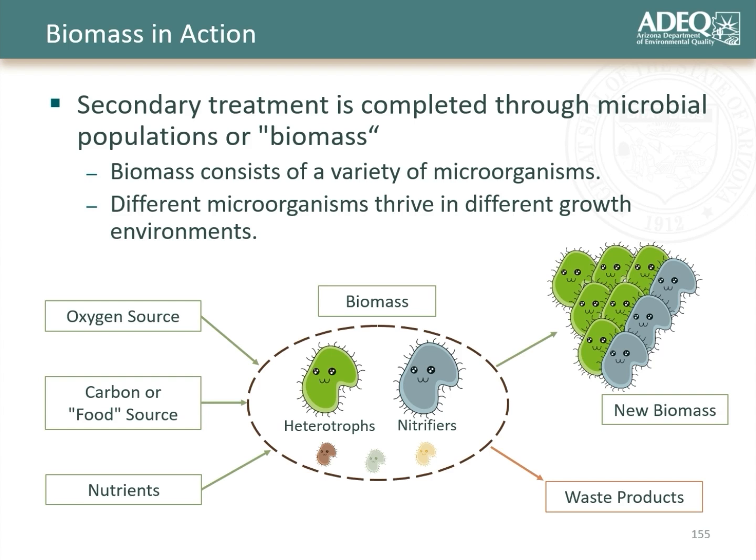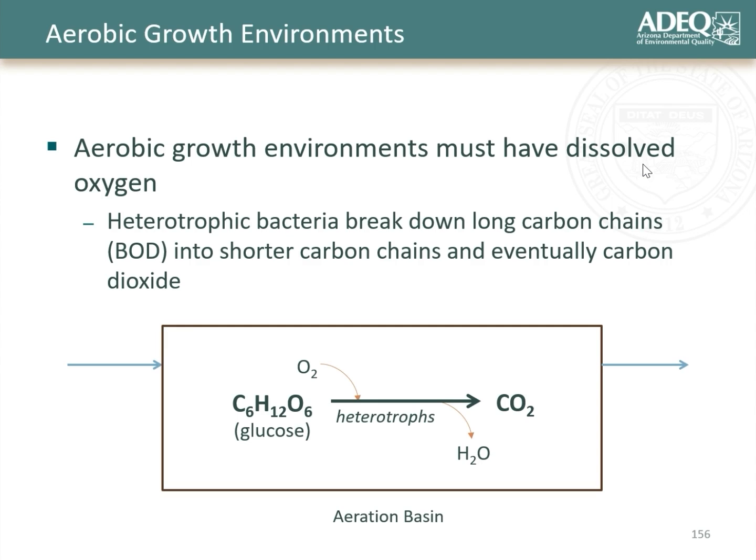These particular bacteria, which are the two key ones that we mostly focus on, when we think about what they're doing, they're taking carbon source or their food source, which is the wastewater, plus nutrients, which are also present in wastewater, and oxygen that we deliver to them. They take that as inputs and they produce new biomass. So they're converting all that carbon in the food into new biomass and then some waste products as well, is what they're doing.